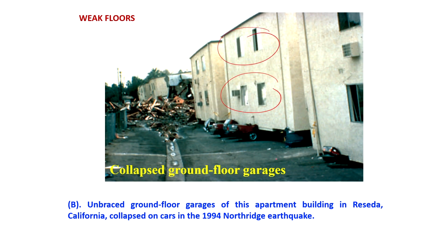So, ground was 1 story, and again, this is what we saw in the last slide. So, you had 2 floors and then you have the open story here. This open story was not at all advisable, and this happened in the 1994 Northridge earthquake. So, this is exactly what we were talking about, that the open ground floor is not advisable.